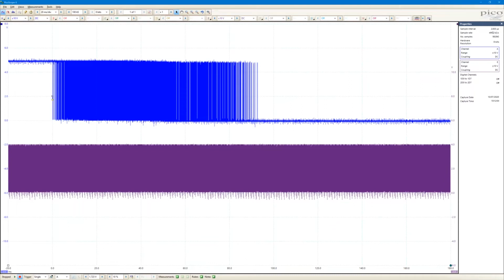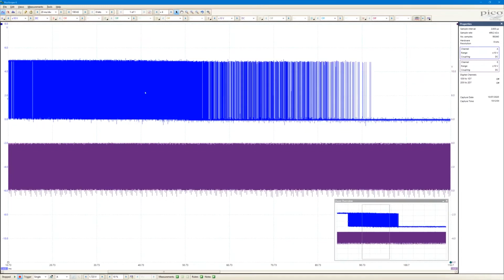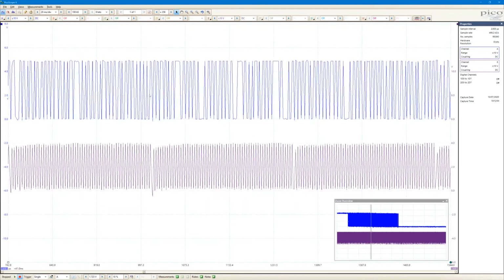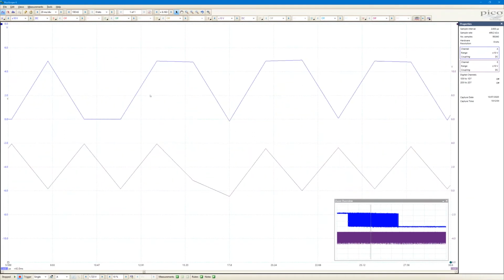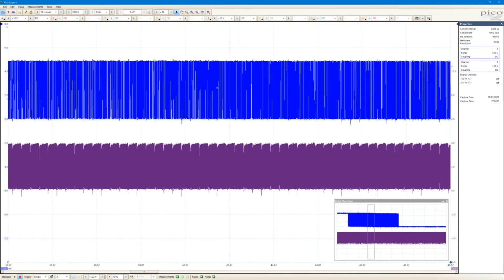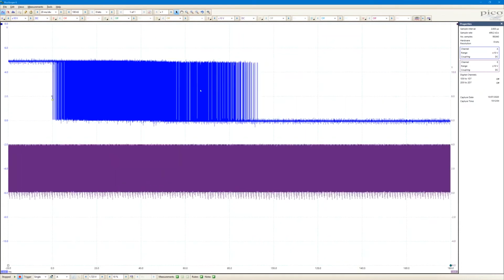So the interval between each sample point was 2 microseconds, which if you're looking at the block as a whole, it doesn't really matter. You can see the extremities of the block of pulses, no problem. But if you want to zoom in to look at the details of what's going on in each one of those pulses, you can see actually each one of those points on the screen now that we've zoomed in by 8,000 times, each one of those points on the display is a single sample point. We're not really seeing the detail of the pulses that we might be interested in.